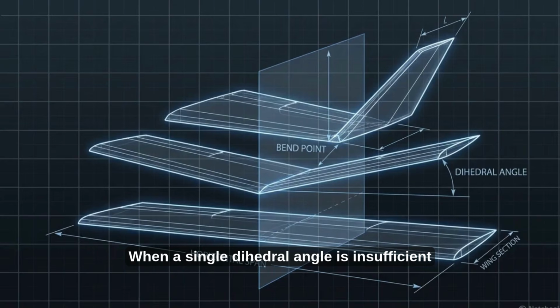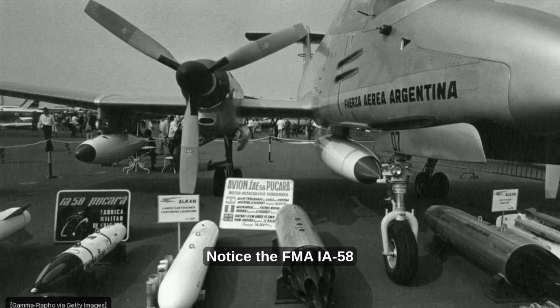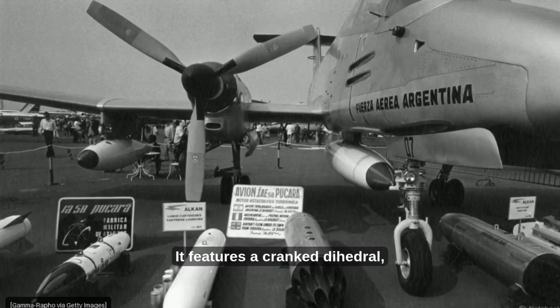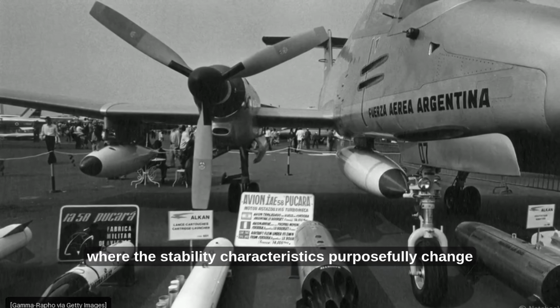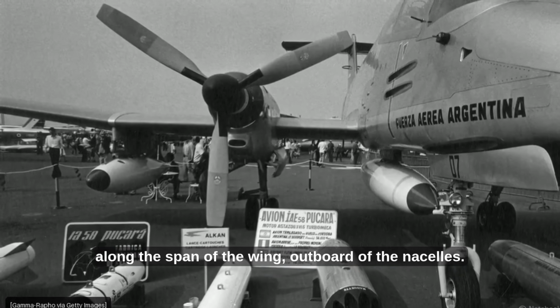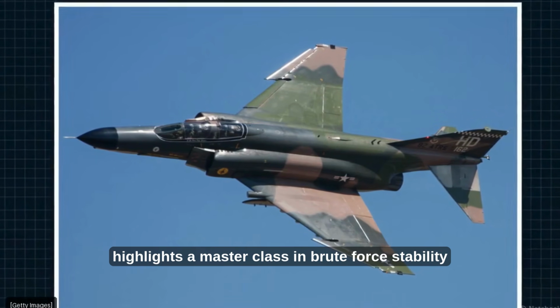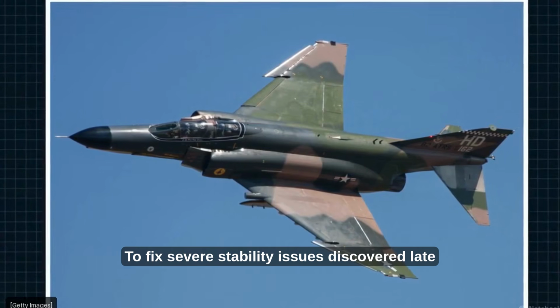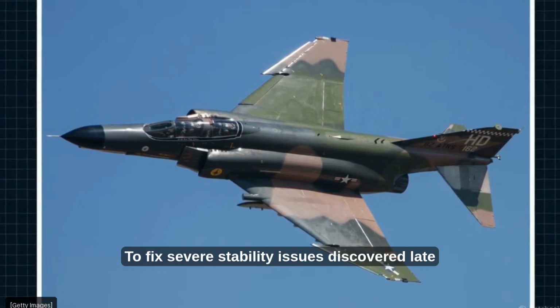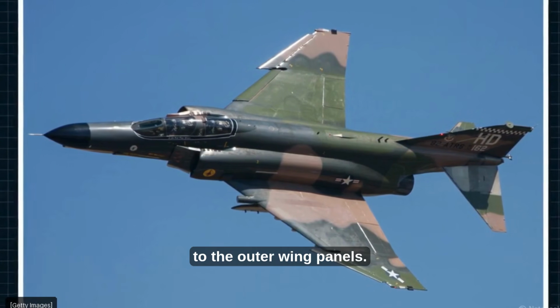When a single dihedral angle is insufficient to balance these forces across complex flight envelopes, designers invent hybrid geometries. Notice the FMA IA-58 Pucará in this photo. It features a cranked dihedral, where the stability characteristics purposefully change along the span of the wing, outboard of the nacelles. This image of the McDonnell Douglas F-4 Phantom highlights a masterclass in brute force stability tuning. To fix severe stability issues discovered late in testing, engineers applied a cranked dihedral strictly to the outer wing panels.